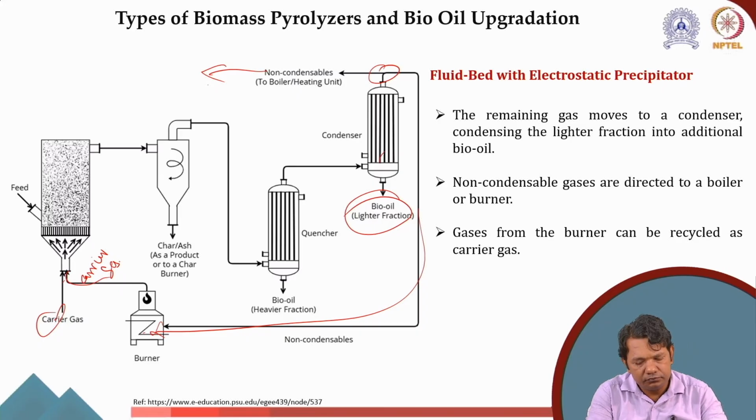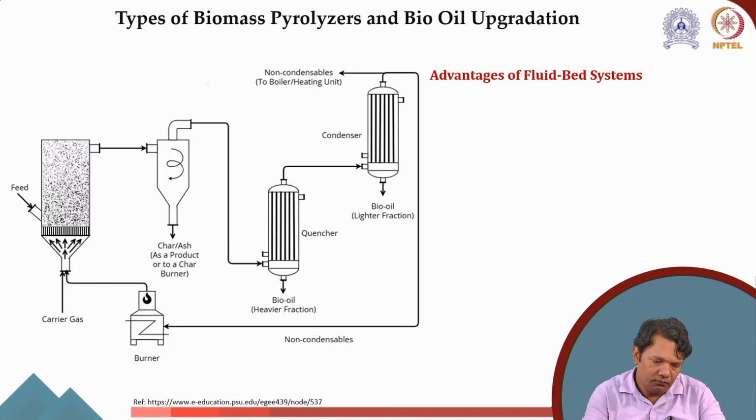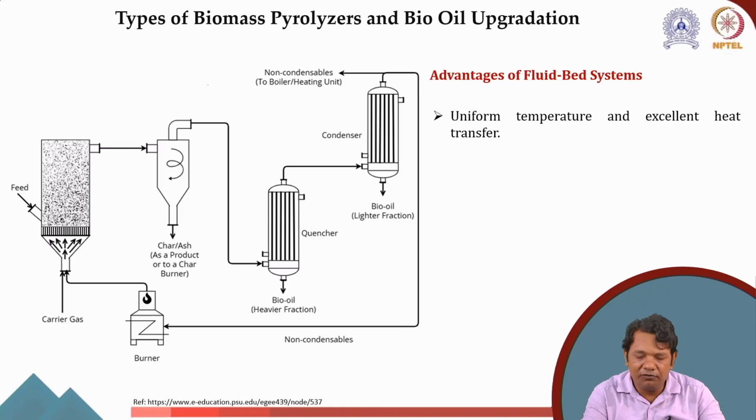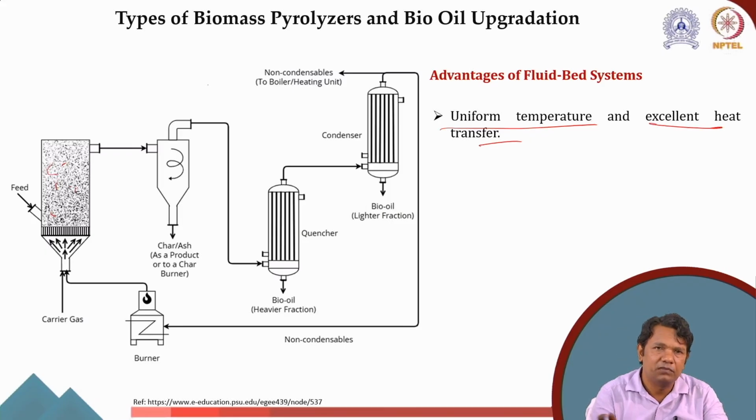Now, let's say if I have a different configuration than this, then what will I do? Or why should I use the fluidized bed system? The primary advantage of the fluidized bed, as I told you earlier also, is that it has uniform temperature and excellent heat transfer. Because the particles are moving here, it is getting heat from all directions, and all the surface area is exposed compared to a larger particle size.